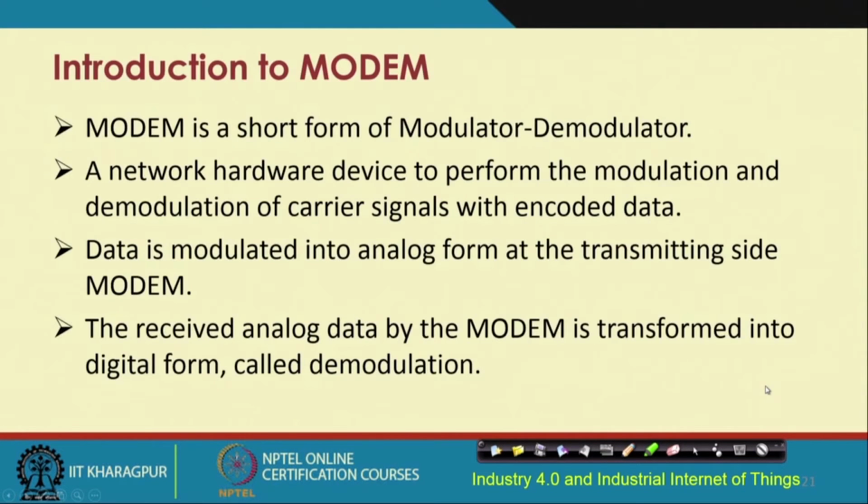Modems are quite popular. Modem stands for modulator demodulator, which is basically a device that will do modulation and demodulation of carrier signals with the encoded data, and this data is modulated into analog form at its transmitting site, and the received analog data by the modem is transformed into the digital form at the demodulator side.